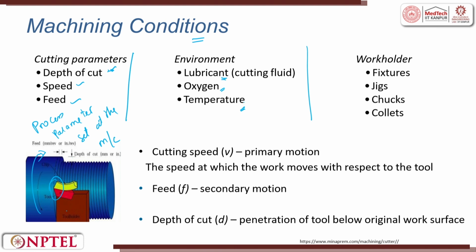As we saw in the first course, when the temperature is applied, there is a softening of the material. So if you can apply heat prior to cutting, then it softens the workpiece, and the moment it softens the workpiece, your forces will go down. So this talks about the temperature.